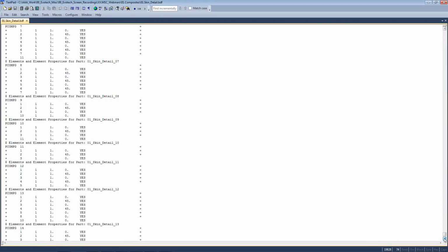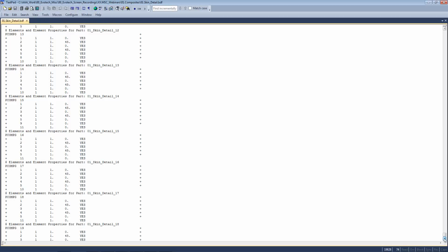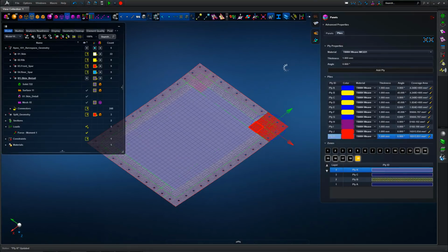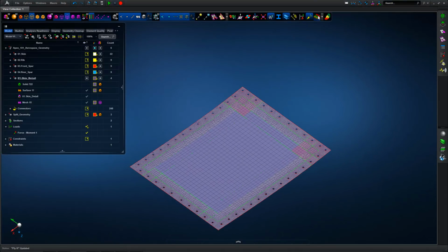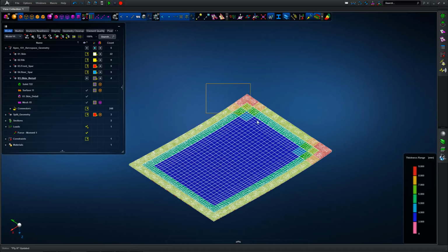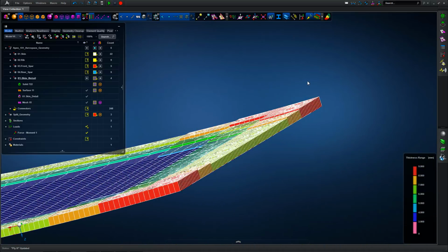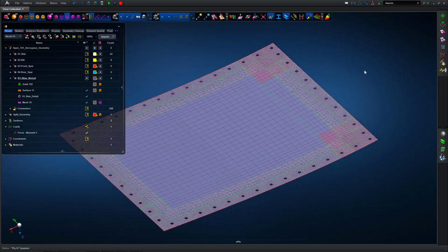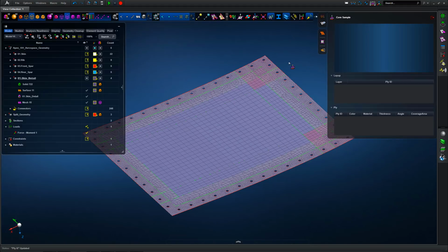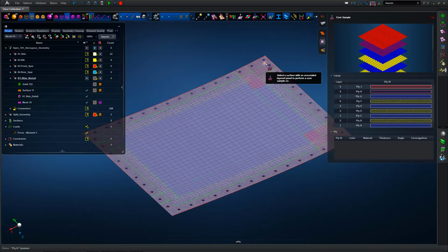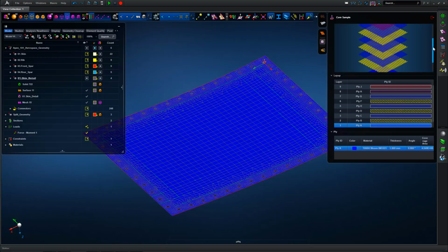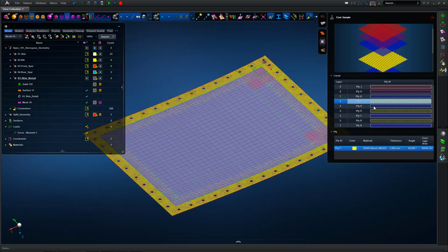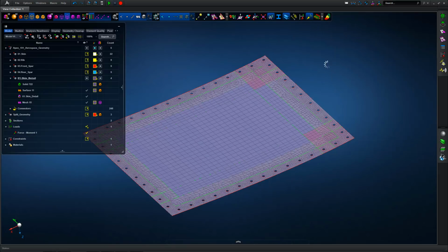And again, if you write the deck out, you can see the reams and reams, well, in fact 19 discrete patch plies or discrete P-comps that have been created to reflect the original laminate with the patch modifications that we've just made. So again, we can look at the 3D thickness, and again we now have the 7mm with 2 plies on it, so it's gone up to a 9mm thick definition in the corners where we want the additional material. And again, using the core sample tool, we can see the color coded new plies as they've been defined, and we can cycle through the core sample to show the extent of the ply.